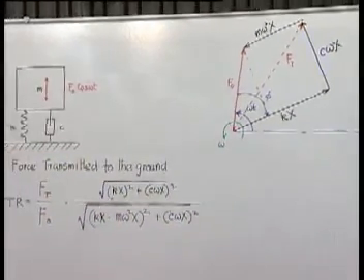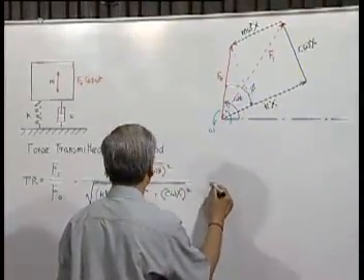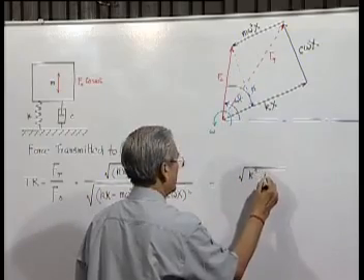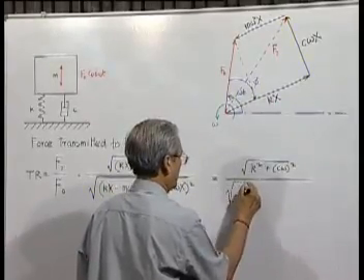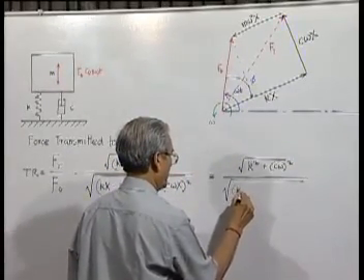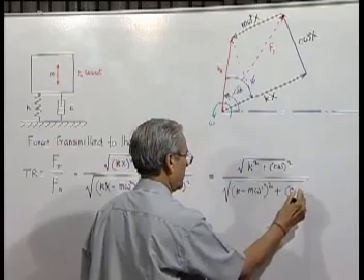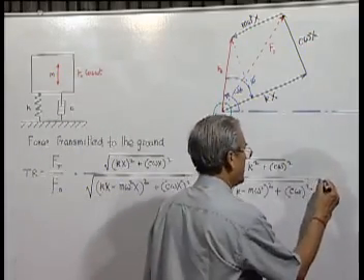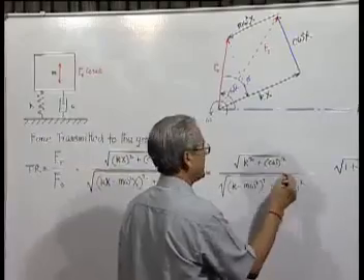So this is the ratio of the magnitude of the transmitted force with magnitude of the generated force, and if we take x common outside, it goes out and it becomes, and you definitely have guessed by now that we are going to get the same if we divide by k square or take k square common outside, then it becomes 1 plus c omega by k is 2 zeta r.